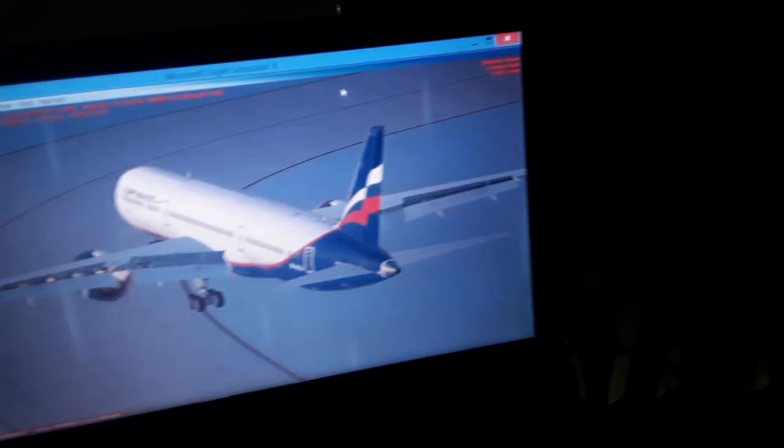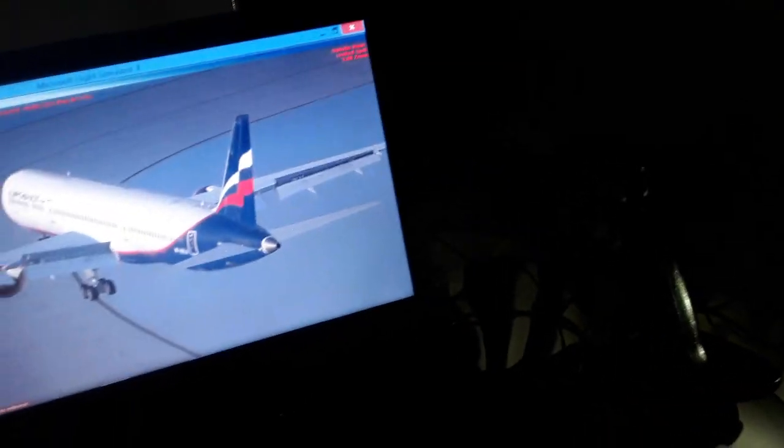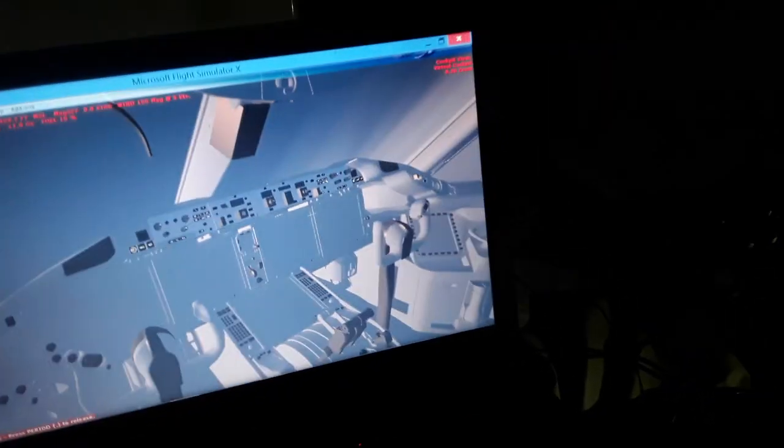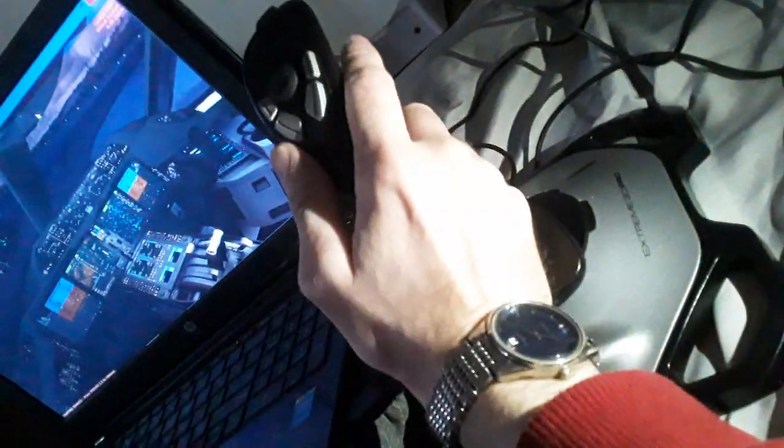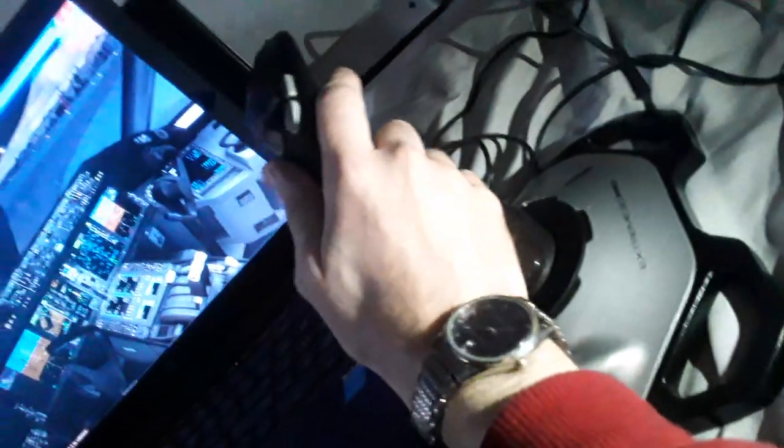After finishing all the systems functions we need to know. So I believe this is enough for the flight controls tonight. This is side deflection proportional to the yoke, both captain and first officer moving together. In flight they're interconnected. They're not like in the Airbus where you have the side stick priority for either side.